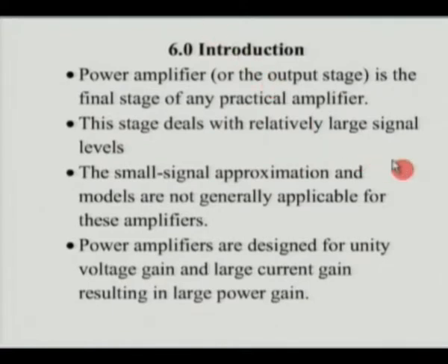Now let us get some idea about this topic of power amplifiers or the output stage in an amplifier. The power amplifier or the output stage, as I said right in the beginning of my lecture, is the final stage of any practical amplifier. Why is it so? Because in the final stage you have to connect the output of the amplifier to the load. So the power amplifier's main function is to drive the load.